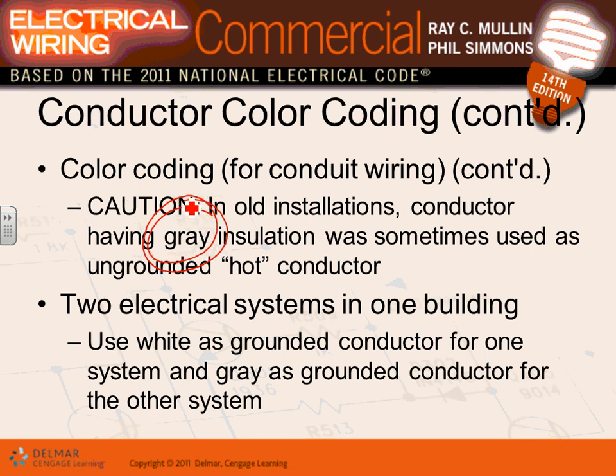If you have 2 electrical systems in one building, the building that you guys have with me, the 15,000 square foot building, has only one voltage system, 208/120. If you have 2 voltage systems, that's a commercial project. We're going to have a 25,000 square foot manufacturing floor. We're going to have 2 levels of voltages. So if you have a voltage of 480/277 and 208/120 volt, these are 3-phase systems.